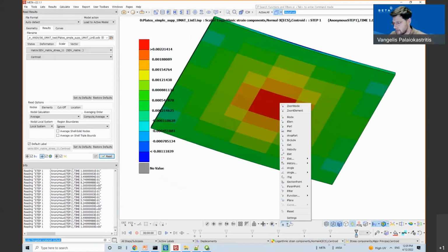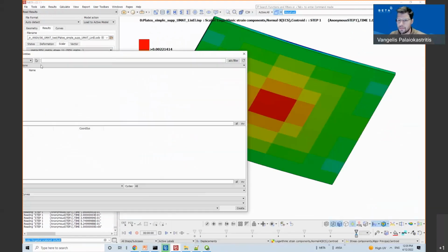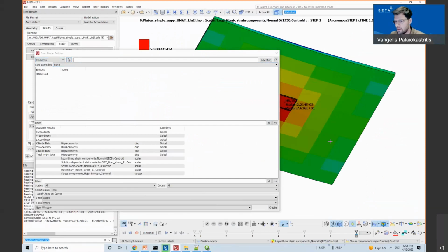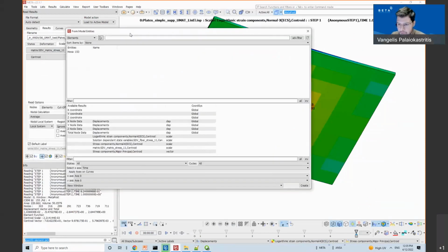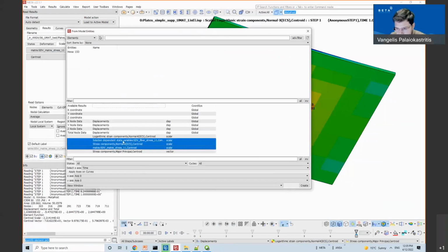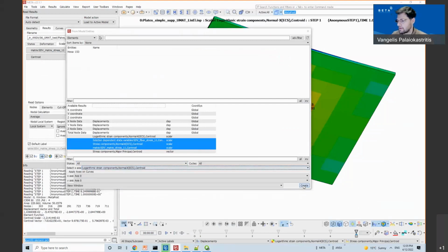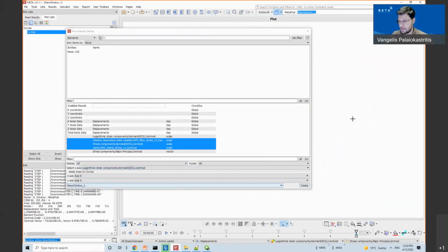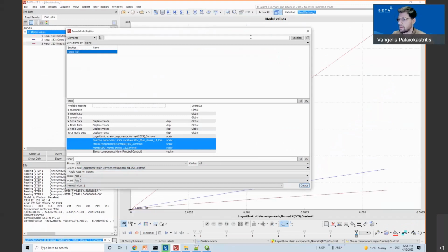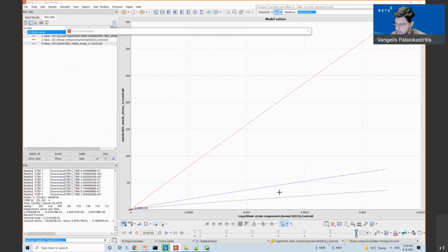So if I now focus on an element and see what has been calculated by the solver through the UMAT, I will plot all the stresses for the matrix, the fiber, and the homogenized versus the strains. Okay. And I get something like this.